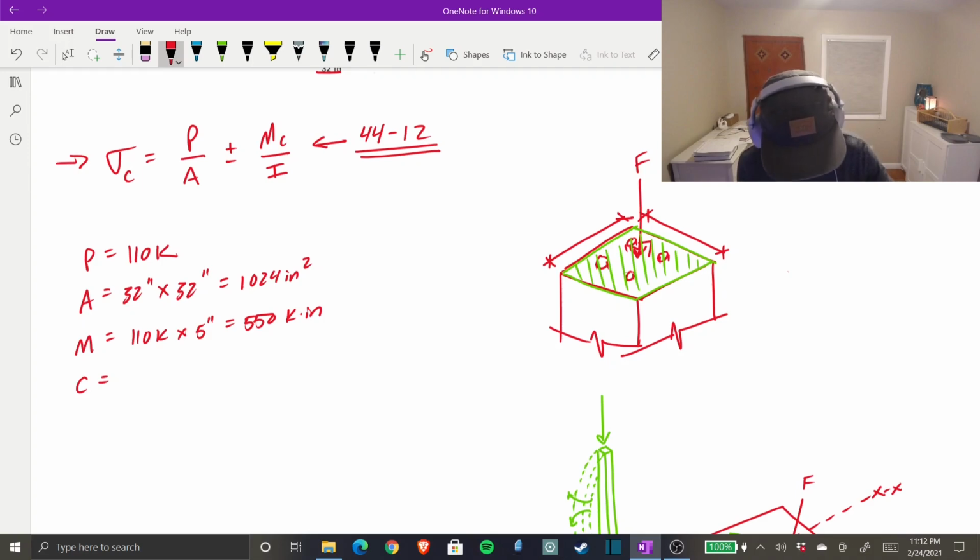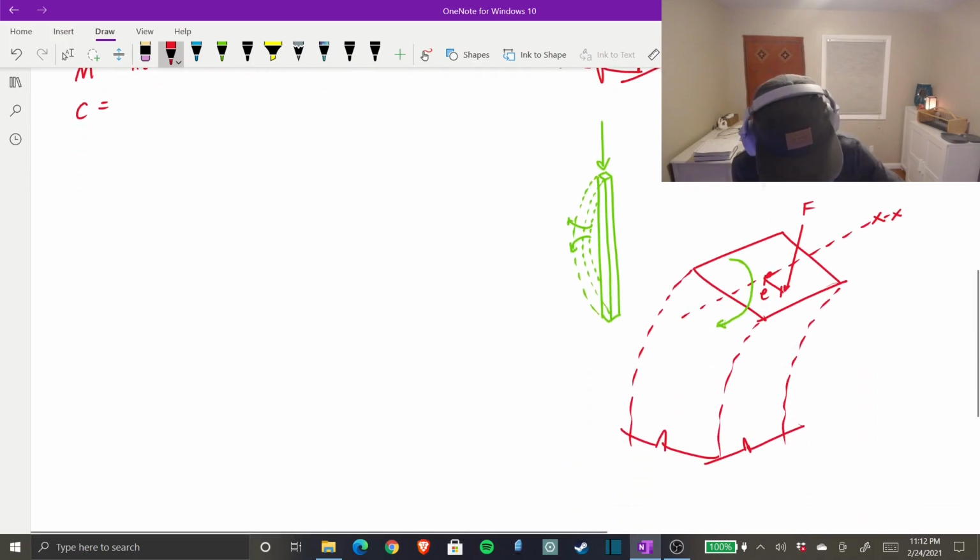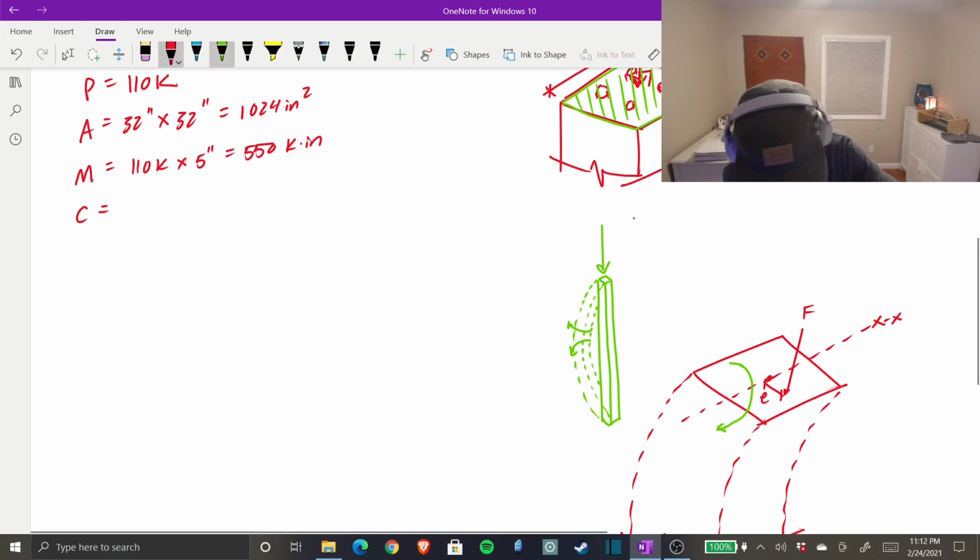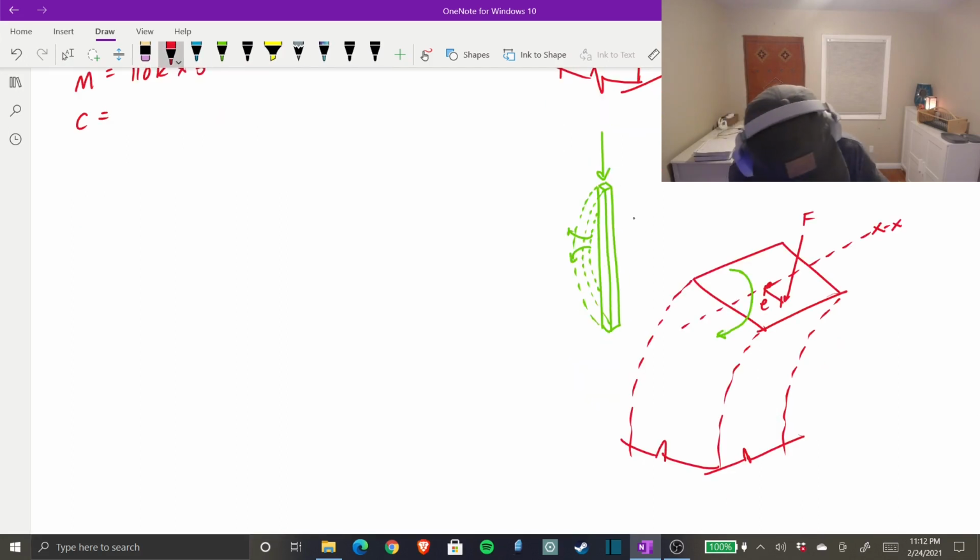If we treated it like a concrete beam, because this just always clicks better in my head, if it was bending like this, you would have cracking that would start to form on that face because you have internal tensile stresses building up, and then you have equal and opposite compressive stresses building up on this face.